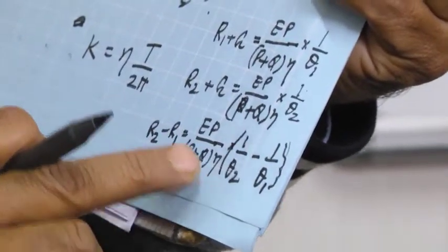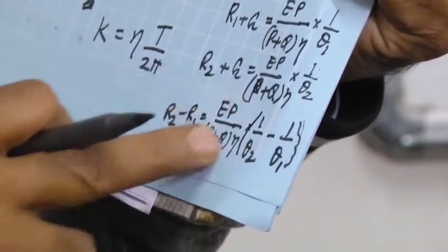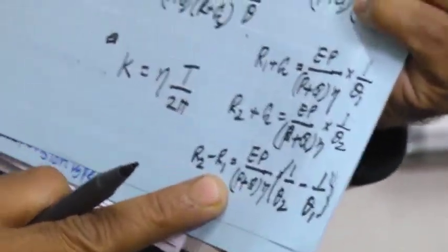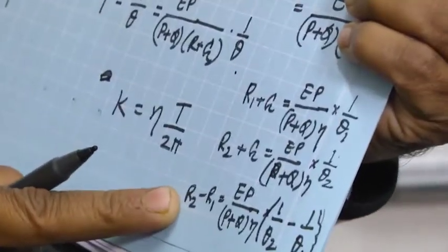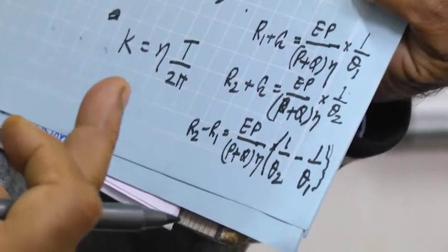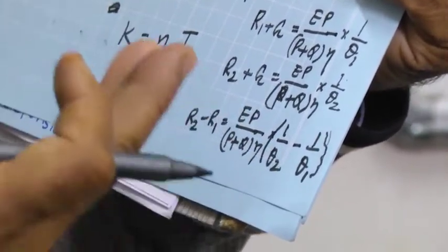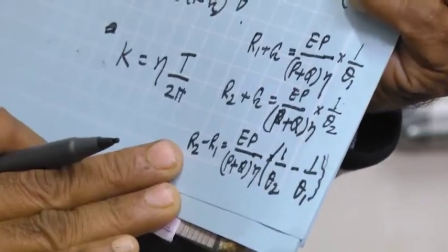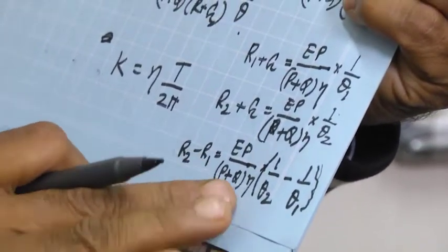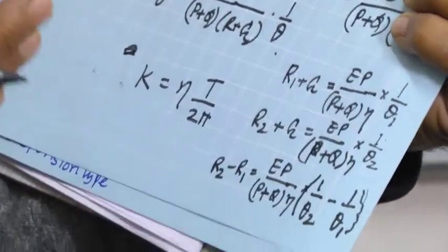Then the other values are known to you. This we are not varying, we are keeping it fixed, only we are varying R. If we vary R, then Ig will be different, and for different Ig, theta will be different. So we will measure theta for different R. That's our task. Then we will find out eta, which will be the current sensitivity.